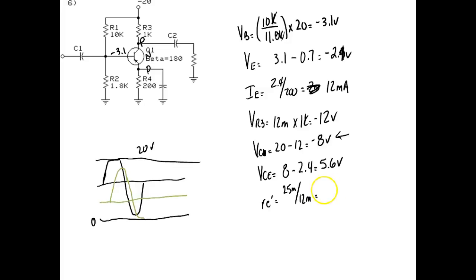What's that? Yeah, that's almost nothing. You can see the higher this guy is, the lower it is. But to get that, we had to choose these resistors very small. So we got a real low output impedance to get a real high gain. Does that make sense? And when you're designing these things, there's a lot of considerations you need to take. We don't want a low impedance amplifier to feed a high impedance load, right? Does that make sense?